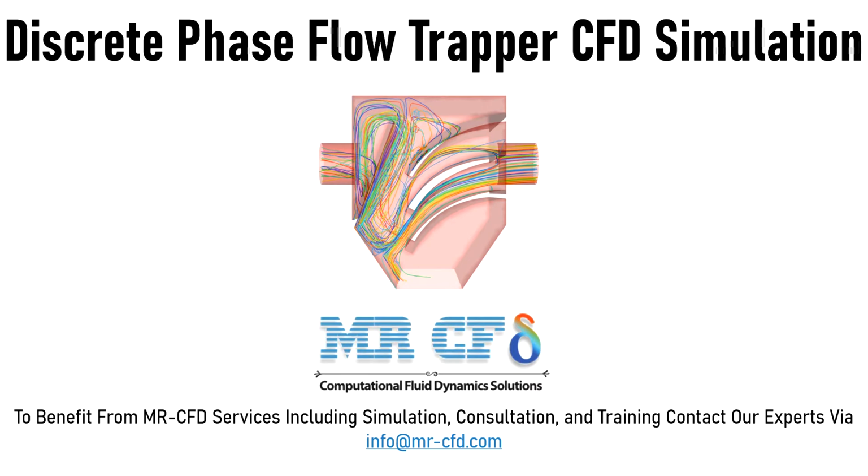The flow containing continuous and dispersed phases enters the computational domain with a speed of 5 meters per second, and the standard k-epsilon model is exploited for solving the fluid flow equations.